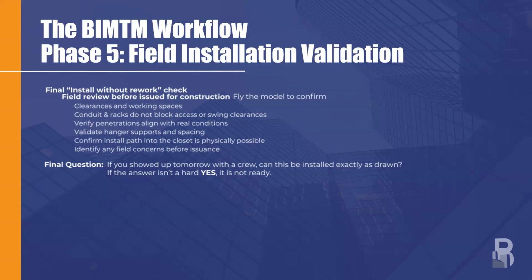We're going to look at the documentation. We're going to make sure that everything is good to go. And the main important part about this is, before it's released, you want your field team to answer this question. If you and your crew showed up tomorrow with the material, can it be installed exactly as drawn? And if the answer isn't a confident yes, it's, we're going to be bouncing back and forth, or material is going to be prefabbed and supplied that they're going to take apart and build separately anyways. Now that defeats the purpose of everything that we're trying to accomplish here.